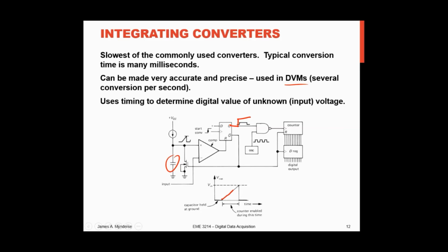And when the capacitor matches the input voltage, which is right there, and it compares in this op-amp, essentially, as soon as this capacitor voltage gets above the input voltage, my output here goes high. And when that output here goes high, it resets this flip-flop. This goes high. This comes low. Okay? So my signal out of the flip-flop is a pulse of some duration.